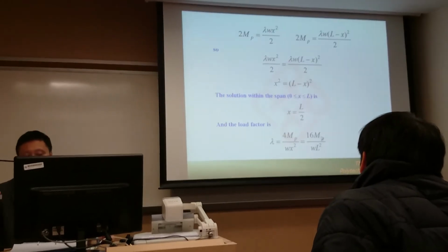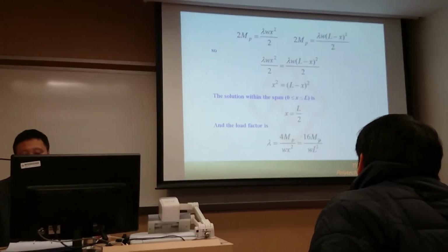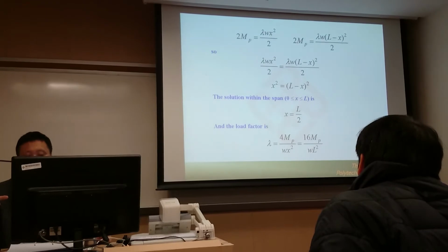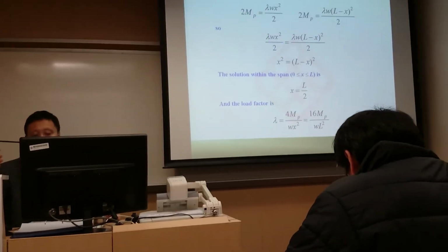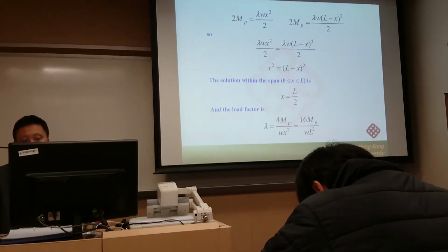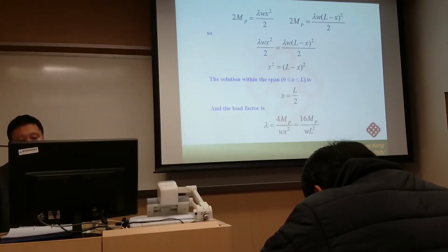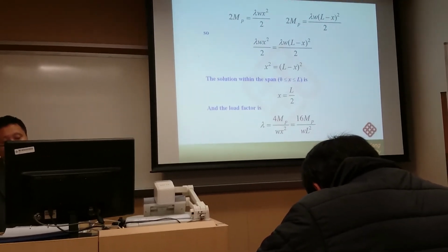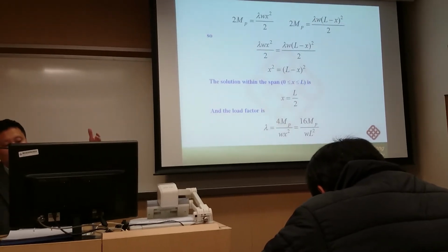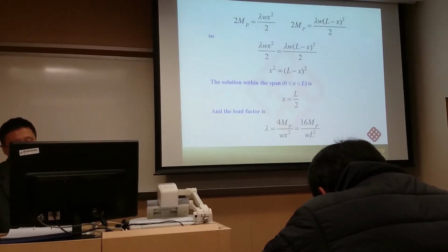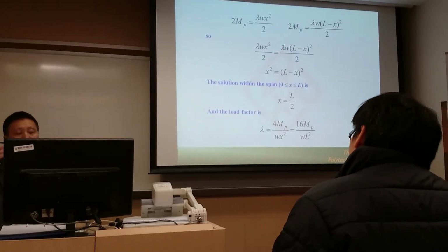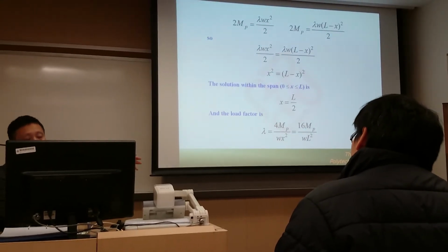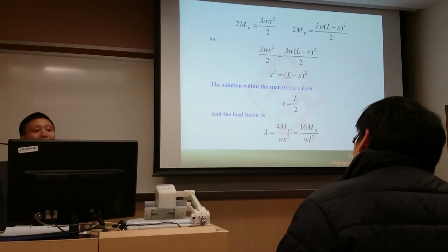When the required MP value has been determined, the MP value over yielding stress is equal to the required plastic modulus, right? So we know the required plastic modulus, and then you can try different cross sections of the beam. When you assume one section of the beam, you can obtain the corresponding plastic modulus, and then compare the plastic modulus from your design and the required plastic modulus.